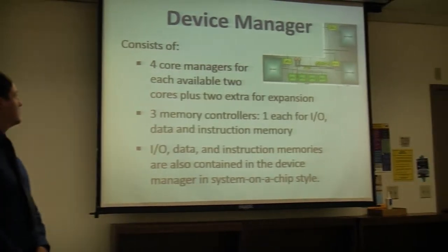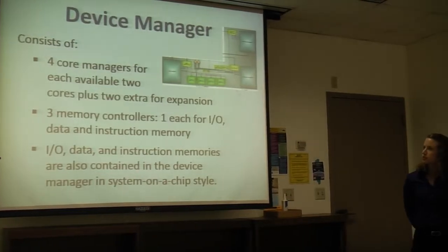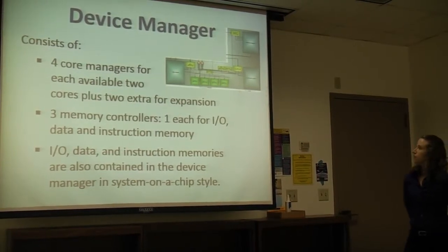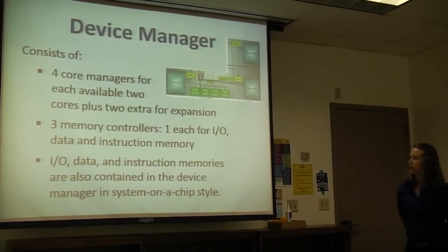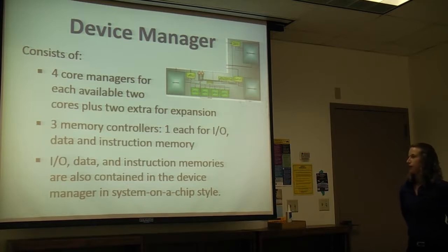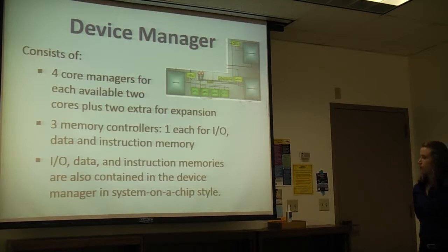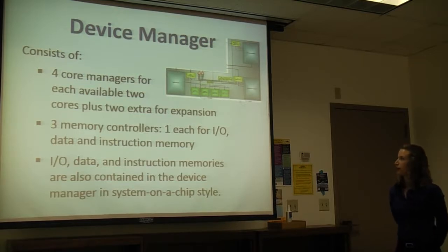So here's our device manager. Our device manager includes 4 core managers, each available for the 2 cores, plus 2 extras for expansion. It also contains 3 memory controllers, 1 each for the I/O, data, and instruction memory. And then finally we have the memories themselves. So it's contained in system-on-a-chip style.